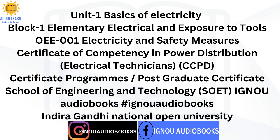In addition to real power, reactive power is also drawn from the electrical energy source to produce the magnetic fields in the motor. The total power consumed by the motor is the sum of both real and reactive power. The units associated with reactive power are called positive vars. VAR stands for volt-amps reactive.